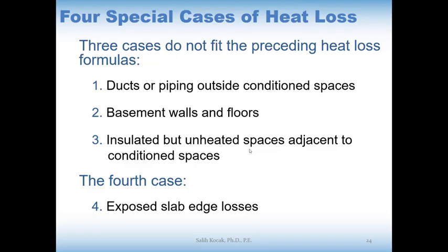The exposed slab edges will fit, with an allowance, the equation U times A times TD, conductance times area times the temperature difference. However, allow an extra 1 square foot of area for each linear foot of slab edge.